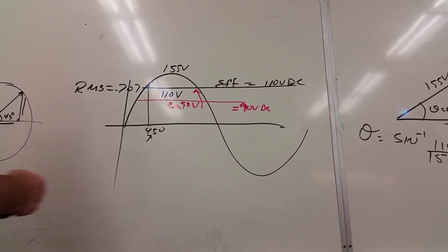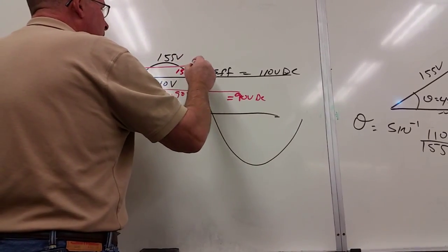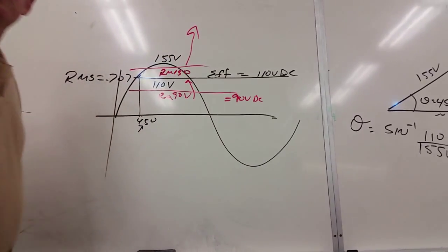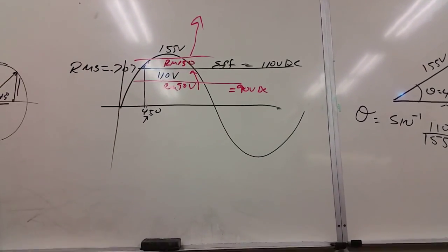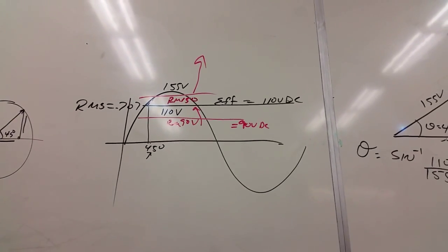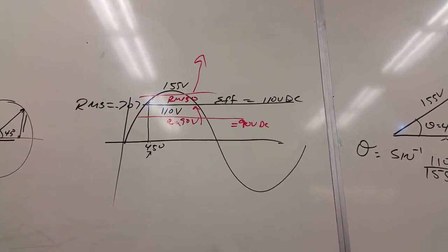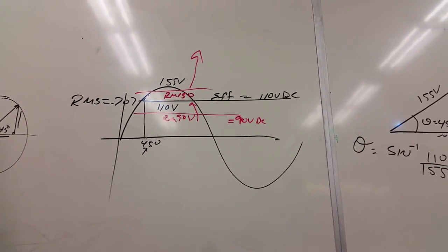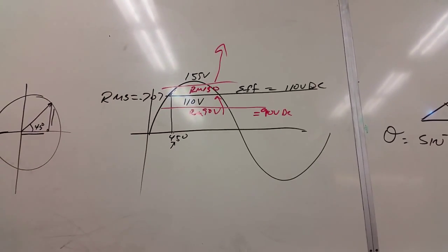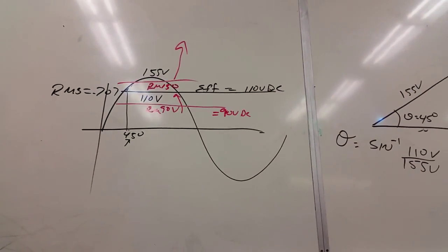Or you may have a problem where it's showing this. And this makes this guy way up here, doesn't it, the peak? And then that's when you start burning up insulation, not because it's hot, but because the voltage is traveling through it. It can short out. All right? So we want to understand what we're actually reading with our meter. RMS, that's a very important value for us.